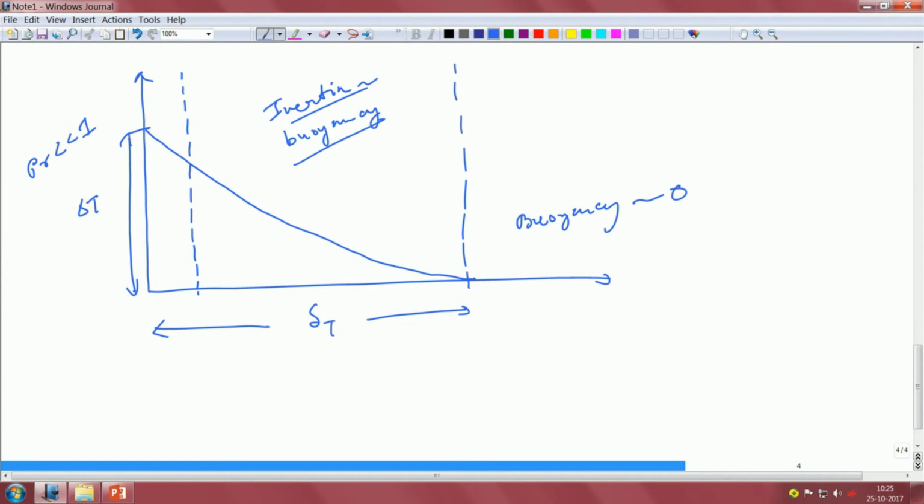In this particular region beyond delta T, because it is a low Prandtl number fluid, there is no velocity possible outside this particular layer, because its inertia driven by buoyancy, inertia and buoyancy are balancing each other. So, beyond this, the buoyancy is obviously going to be 0 because there is no temperature gradient to support it.